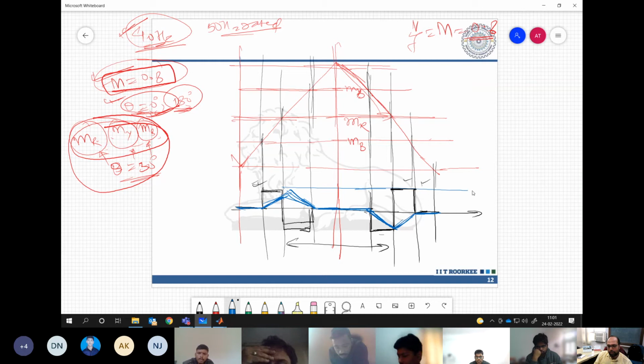So peak to peak ripple is basically coming like this. This is only half peak, 0 to peak. Peak to peak meaning the positive peak to negative peak. This is the peak to peak value. So if asked what is the peak to peak value, you have to tell from the positive peak to the negative peak and not just 0 to peak value. That is why this is highest, because in this subcycle it is going only in one direction. Another half cycle it is going only in one direction.